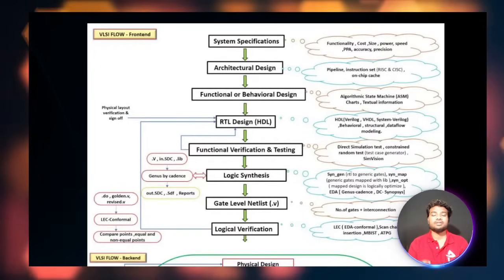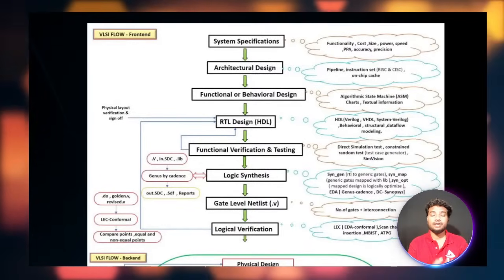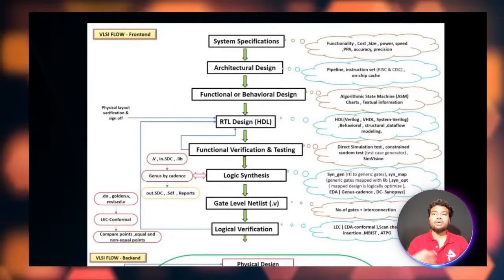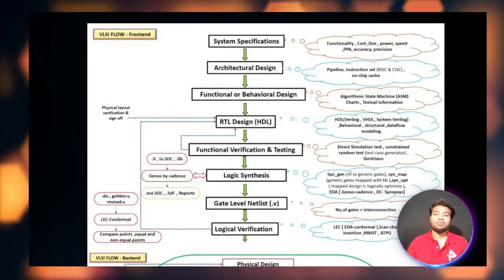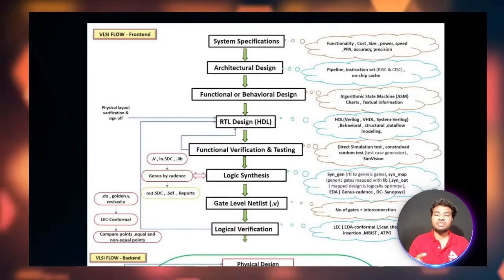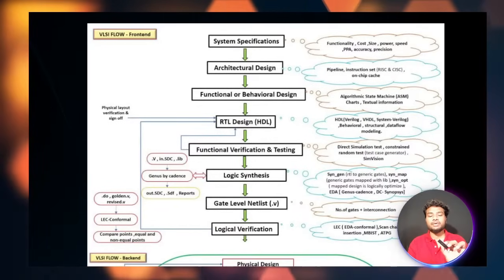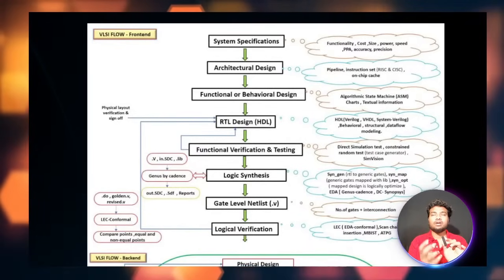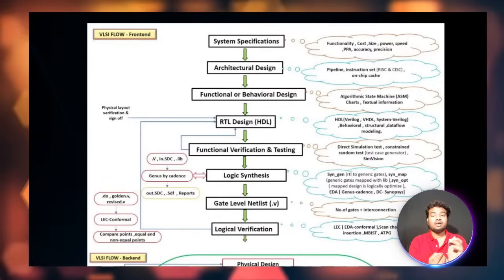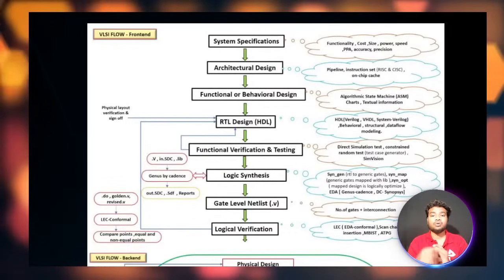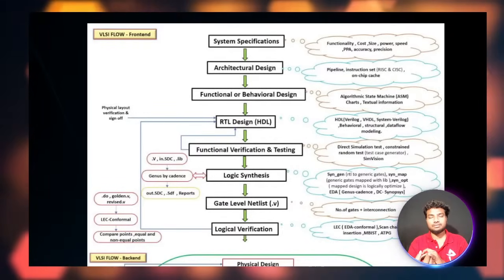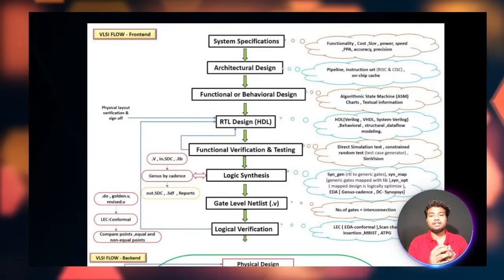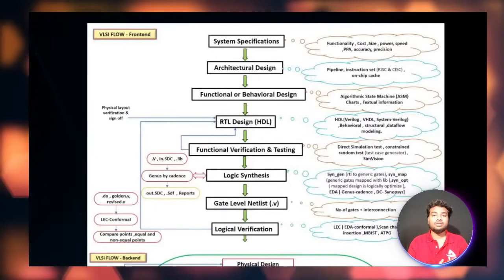For that we have to design the correct logic, and then verify the code itself. Only then can we move into the physical chip making. If you make a chip with a bug, we have to remake the chip, because you can't change the chip's functionality. Once the chip is made, you can't recreate the logic inside it or make any changes. If you want to change, you have to start from the beginning with a new chip. That's why verifying the chip code and the design code is very important.